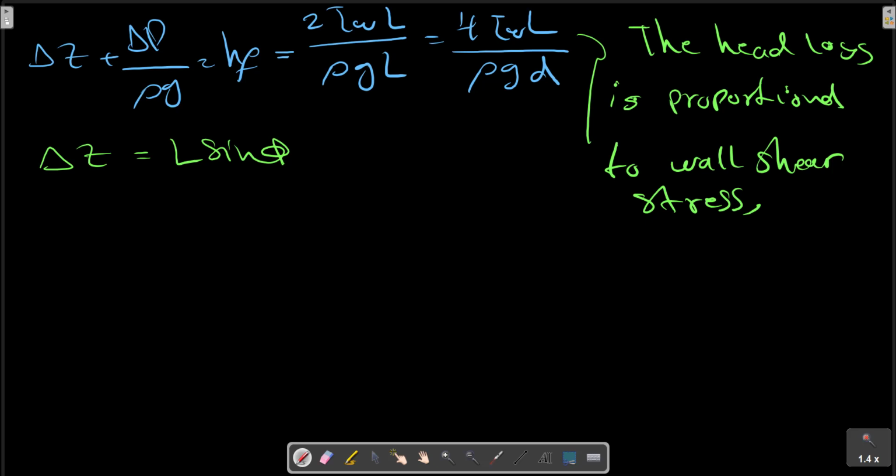How should we correlate the head loss for pipe flow problems? The answer was given a century and a half ago by Julius Weisbach, a German professor. In the 19th century, he published the first modern textbooks on hydrodynamics, and previous relations and data such as Hagen's show that for turbulent flow, head loss is approximately proportional to the square of velocity. The proposed correlation is still effective today as this relation.